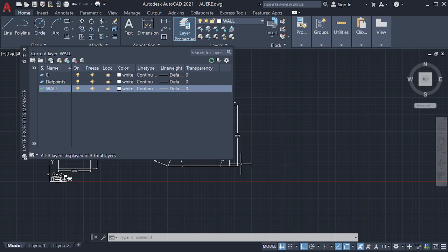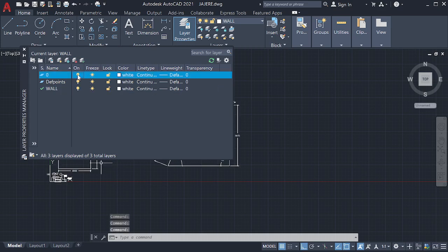You can remember, all that we did here, we did it under this zero or default layer. So once I click on this, definitely all of the layers will hide. Okay, so you can see, I can turn it on and also turn it off if I like. This is great for focusing on a specific part of your drawing. Assuming you have multiple drawings and you want to focus on something, then you can hide one layer and leave the other layers, or hide all layers and leave one layer if you want to do something.